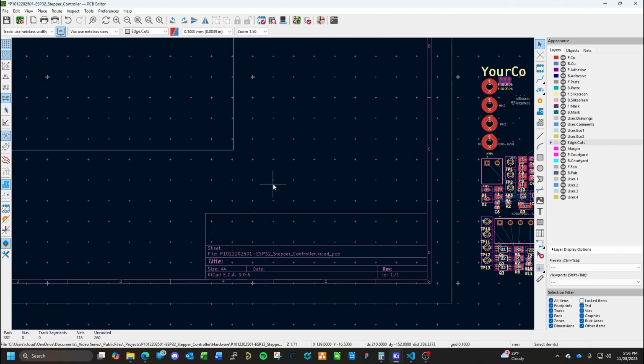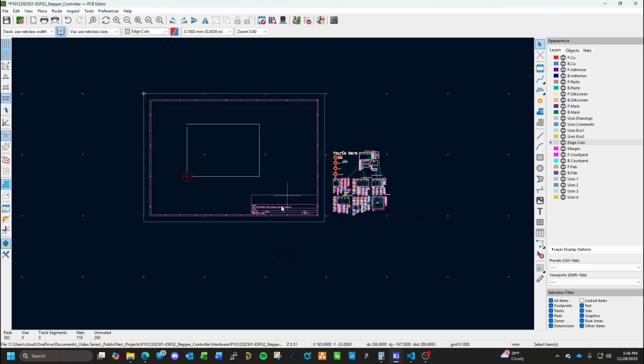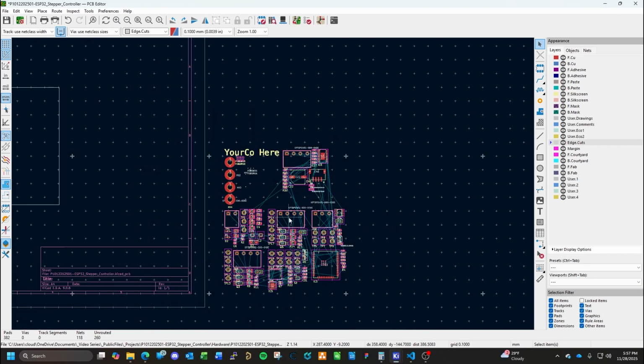I think this is basically letter size. Typically, I like to lay out on tabloid size, 11 by 17. So I might try fixing that later. I'm not sure how. We'll see if we can lay this out. We should be able to. A bulk of the space is going to be taken by the pluggables. Obviously, we've got a bunch of big components in here we need to pull over there and get plugged in. We're also looking at possibly a double-sided board. So we can move things around as necessary for that.